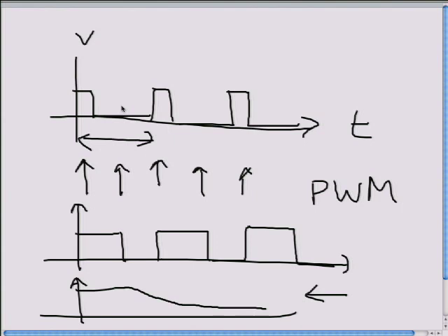First of all, one of the issues is that with motors, if it's a big motor, you've got to deliver a substantial amount of power to it, right? So the circuits have to be able to handle a lot of power, which means either high voltages or high currents or both. And designing circuits that can handle high power over a whole range of voltages is much more difficult than designing circuits that can handle high power at only a single voltage.